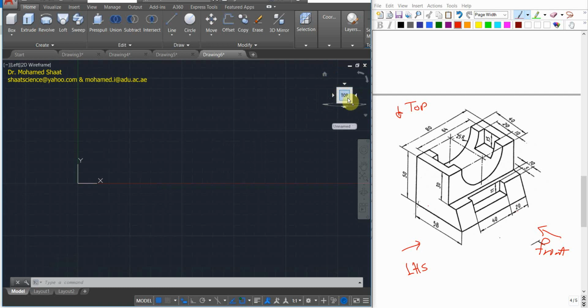No matter, it doesn't matter here. But anyway, now I'm working over the left-hand side of the 3D solid as we agreed before. Then I'm gonna start creating this shape, starting from, for example, this point. I'm gonna assume that this is the 0 point, and I'm gonna draw 58 to the right, up 50, right